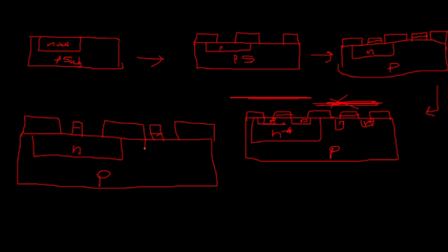Till now these dopings are done. Now the substrate connection is remaining. For the N type it will be N plus, a little highly doped, and if this is the P type substrate, then it will be P plus, and then the connection will be done. So your PMOS will be connected to VDD.